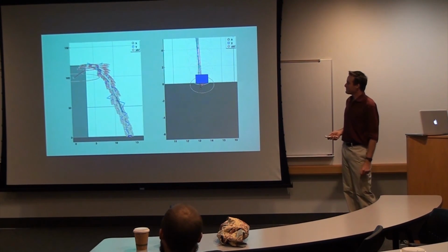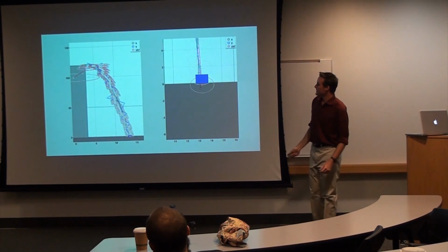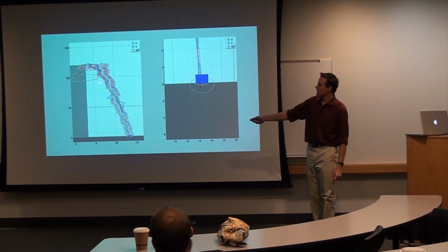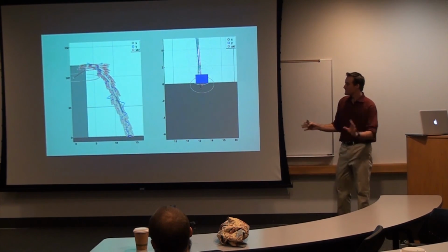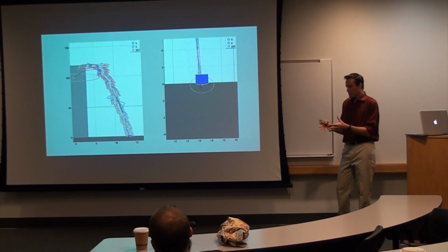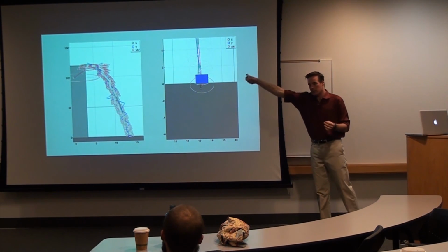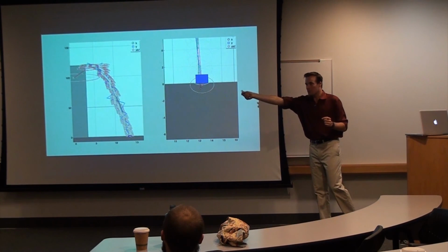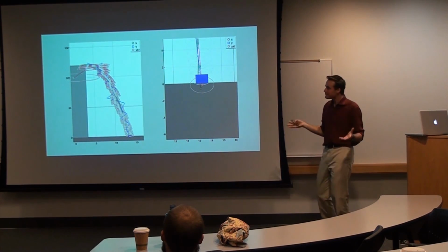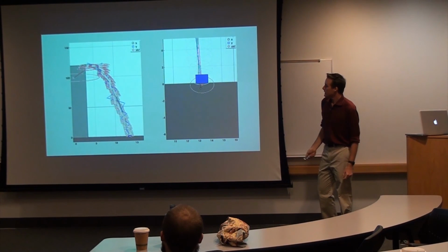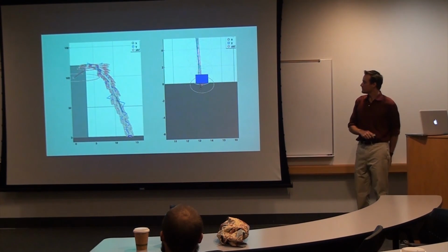So I guess just a couple of things to note here is that initially the covariance, the uncertainty in the estimate, is quite large, and with each additional measurement, it gets smaller. But it never gets all the way to 0, and in a hand-wavy sense that's because the estimator knows that there's always some measurement error and there's always some disturbance pushing around the state. The state is constantly moving and jiggling around, so it can't zoom in perfectly on the state. Yeah, and I think that's pretty much it.